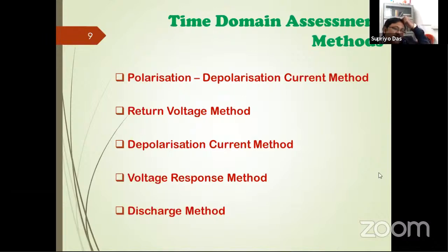Now coming to the methods, what are the methods in time domain assessment? The most common and most widely used method is the polarization depolarization current method. There is the return voltage method, the depolarization current method, or we can say isothermal relaxation current analysis, the voltage response method, and the discharge method. All these methods come under the time domain assessment.